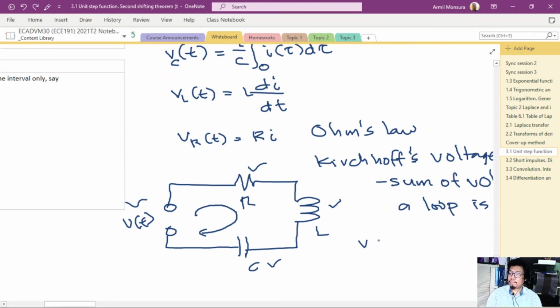If your current passes through this resistance, the voltage would drop right there. Okay, there would be a considerable voltage drop. So that voltage drop actually lessens the source, so that after your current passes through the resistor, you would now have V minus VR as the potential after the resistor.